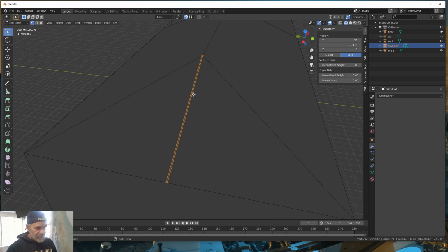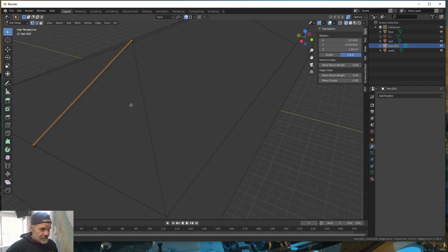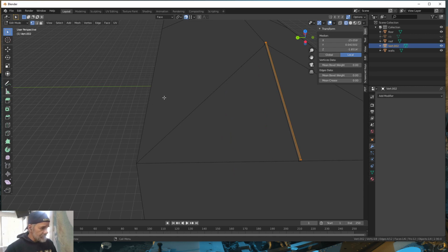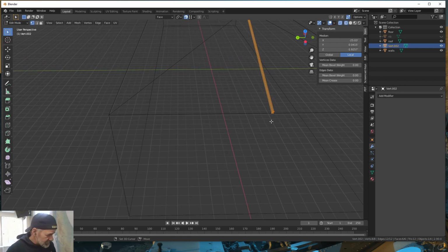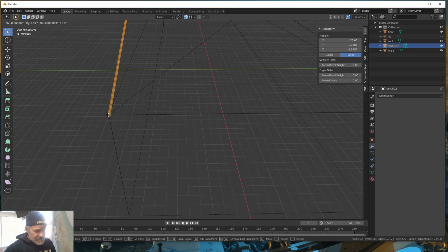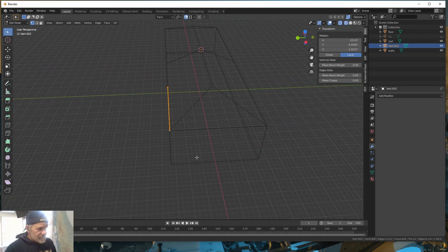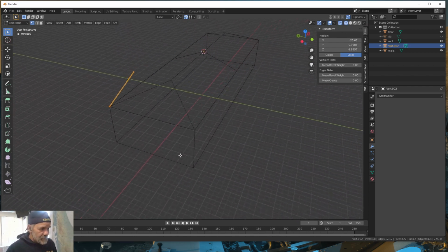Then, now with my polygon selected, I can extrude 0.16, and now I have a rib at the end of the building. And then, like our other one, we want to turn on X-ray, select all of our vertexes for this rib, zoom into that corner, and select this vertice, and we want to move our entire object to this corner, so hit G since I have node snapping on, vertex snapping on, hit enter. All right, so that starts our ribs for our ends.